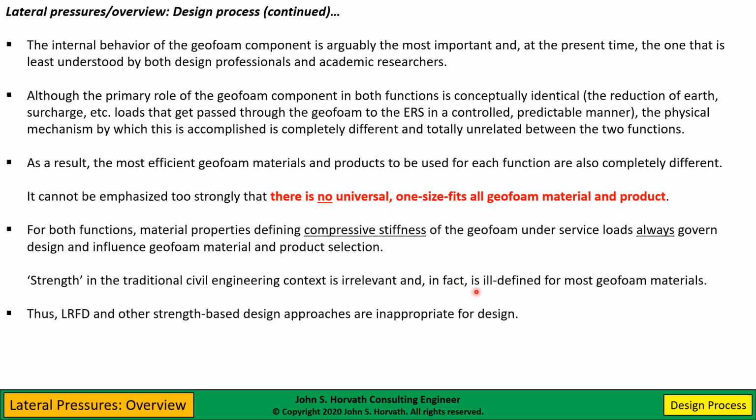In my opinion, LRFD and other strength-based design approaches are completely inappropriate when you use geofoam to reduce lateral pressures on a system. I know there are people who are LRFD fans who feel that you can bend LRFD to fit any design scenario. I really don't feel this is one of them.